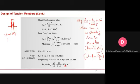In this case the effective area is equal to the net area by this relationship, and this is valid for the bolted connection. If you have a welded connection, in that case you will use this other relationship for the effective area.